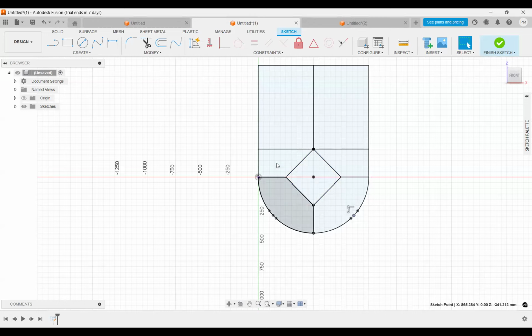I divided it into 7 blocks, and we have to create vertices for each point on the back face and front face, and create the arcs. This is how my simulation result will look. Still, I have a little bit of skewness issue.